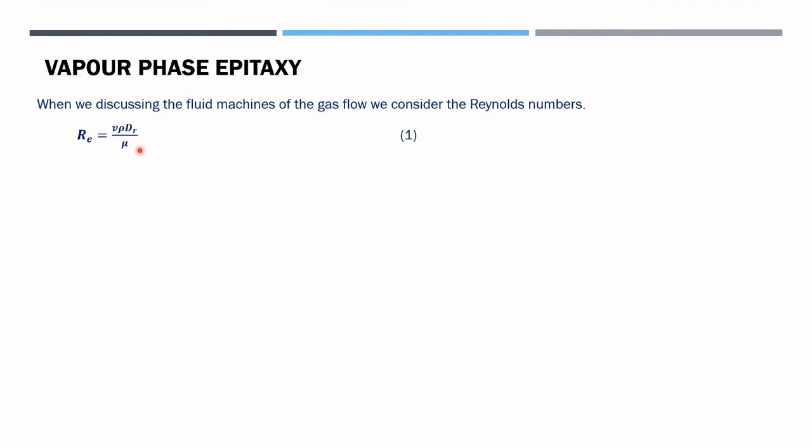Right. So in the reactor I have a stagnant boundary layer, and the thickness of the stagnant boundary layer is a very important criterion. The thickness of the boundary layer is defined by y equal to x dr divided by Re to the power half, where x is the distance along the reaction chamber, dr is the diameter of the reaction tube, and Re is the Reynolds number.